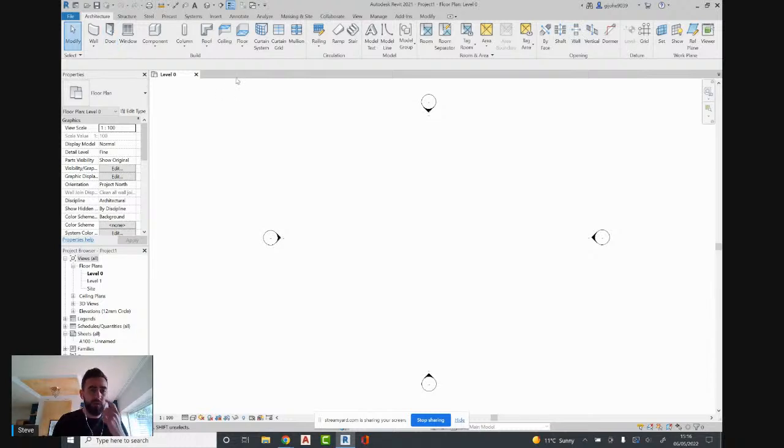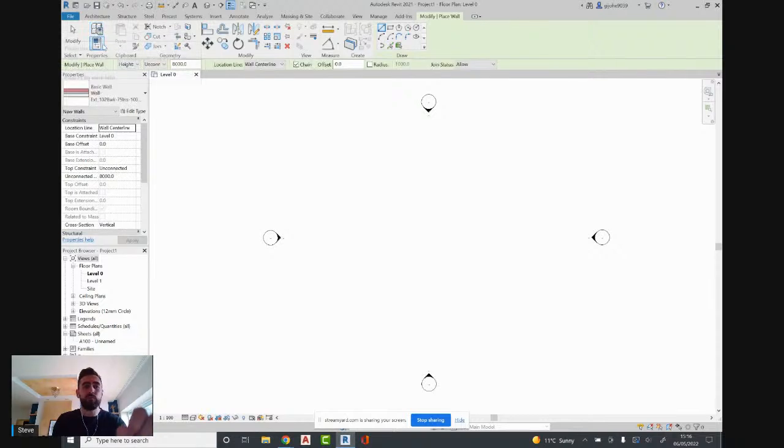First thing, with our build panel and how we create our model, all of the steps are the same. If we want to build a wall, we select the wall tool, and we'll see that the ribbon has changed, but every other tool will be the same. We have a modify panel of how we can modify what we've just selected. And towards the end, we have our draw panel, so how we want to draw it. If you choose a wall or a window, it will be the same modify panel, but then this draw panel will be how you want to place it.